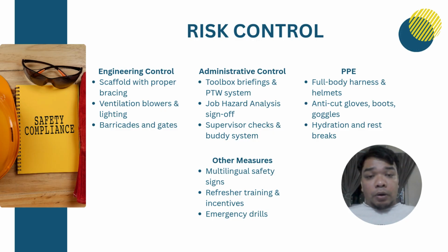Next, PPE or personal protective equipment was essential. All workers wore a full body harness with double lanyard, safety helmet, anti-cut gloves, safety boots, and goggles. To prevent heat stress, hydration breaks and rest periods were scheduled regularly.